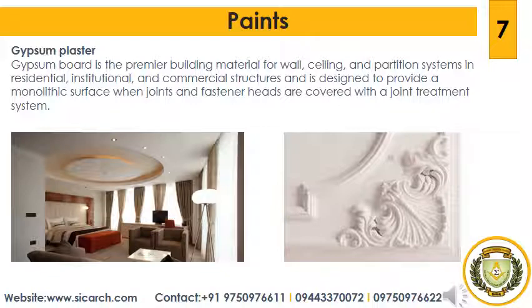It is a fire resisting material and it does not allow heat to pass through easily. Hence, it is used as an insulating material to protect wood or metal columns and beams from high temperature. It is light in weight. To decrease the weight further, fillers such as granulated cork, sawdust, wood shavings may be added to it. Such fillers also improve heat and sound insulating quality of the gypsum plaster.